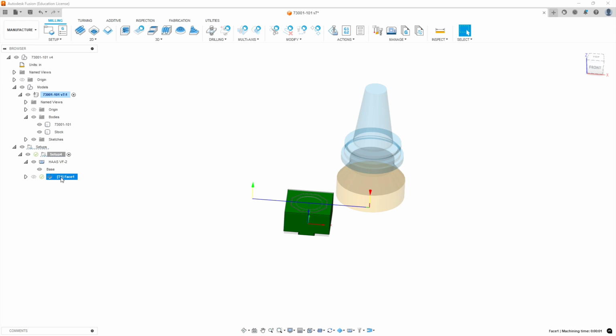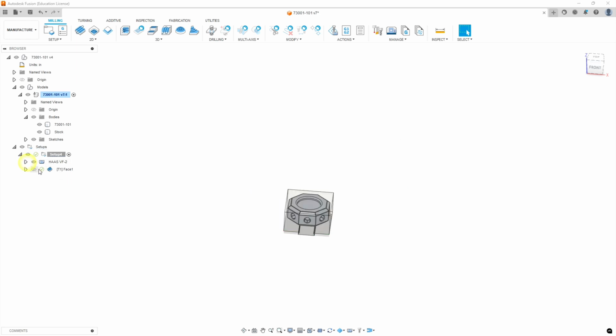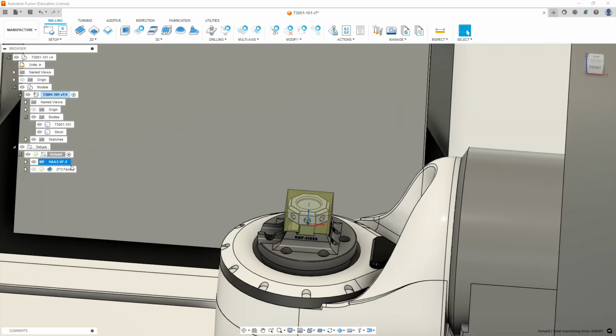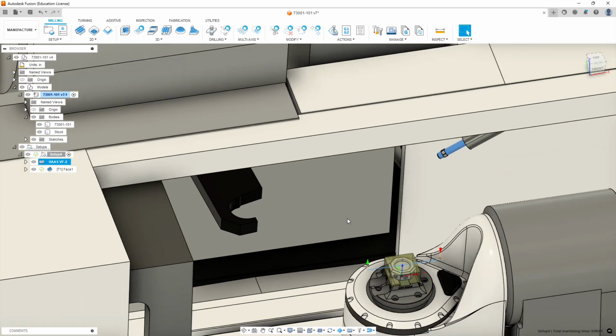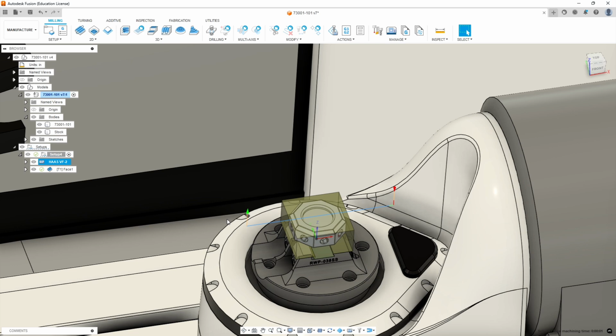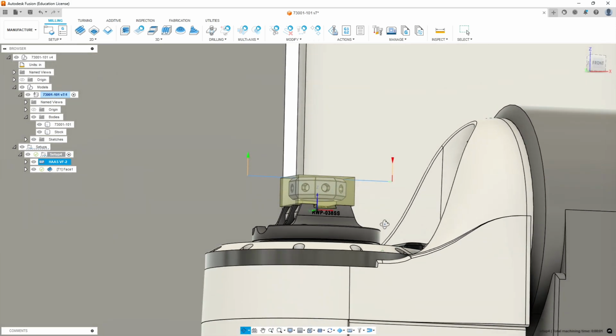I think I'm going to avoid that. We're going to change that. We're going to think about this a little bit more. We want the cutter to go the opposite direction so that we're not risking hitting the fixture. There may be enough clearance, but why push it when we have plenty of room on another axis? So we want this passed around instead of in x-axis, in the y-axis of the machine. To do this, we're going to go back into the routine.